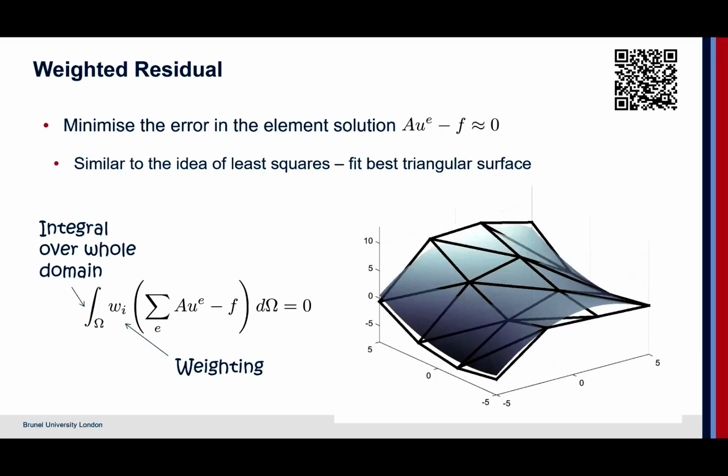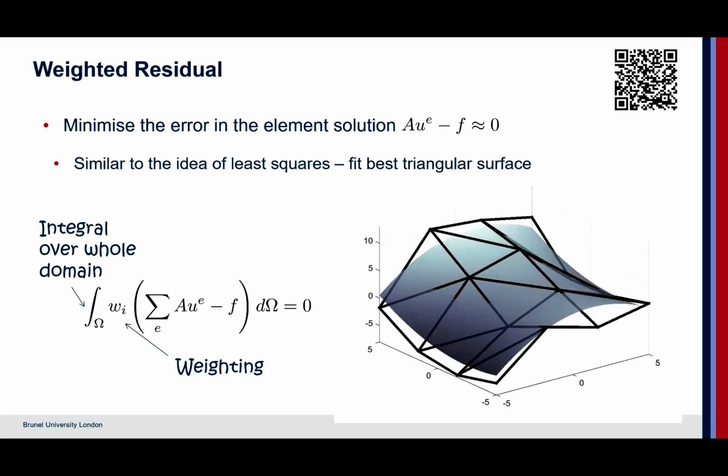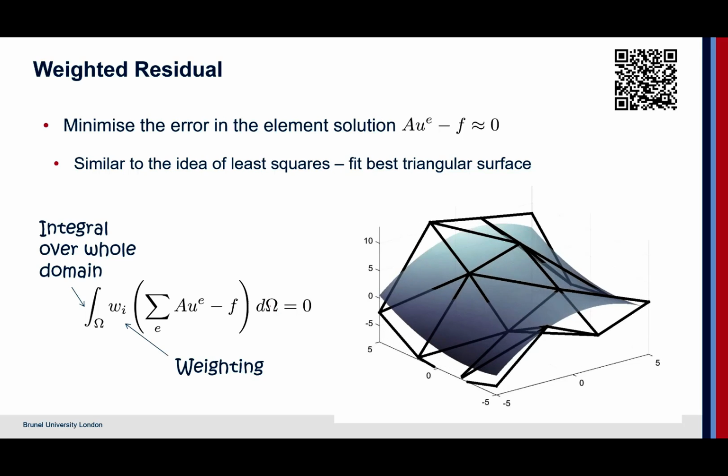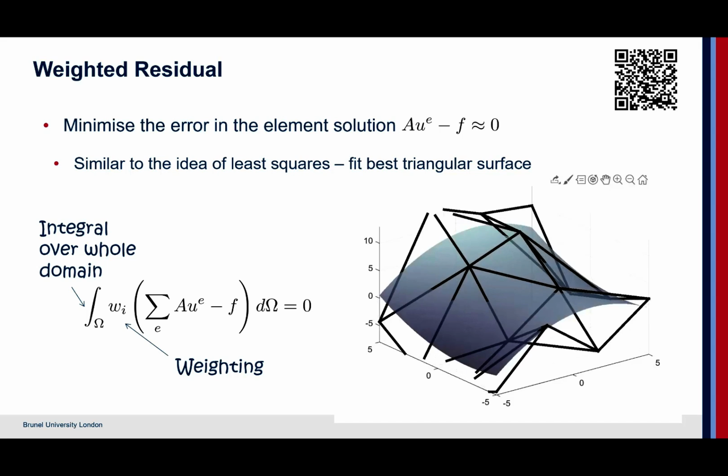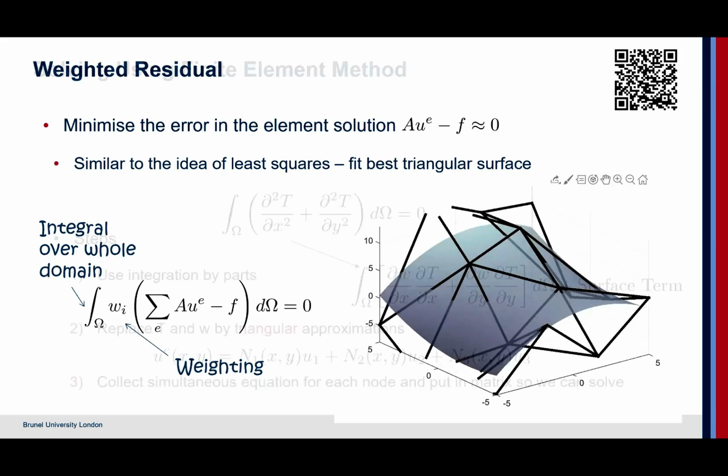And so the process now is one of least squares. We're doing a best fit of the triangular surface, minimizing those weighting functions as we did in 1 dimension, now to fit this approximation to the surface in 2 dimensions. A couple of things to note here is that this integral is now over 2 dimensions. This omega is a general integral. So before we were integrating just over the one-dimensional linear case, now we're integrating over 2 dimensions and fitting that surface to that expression.